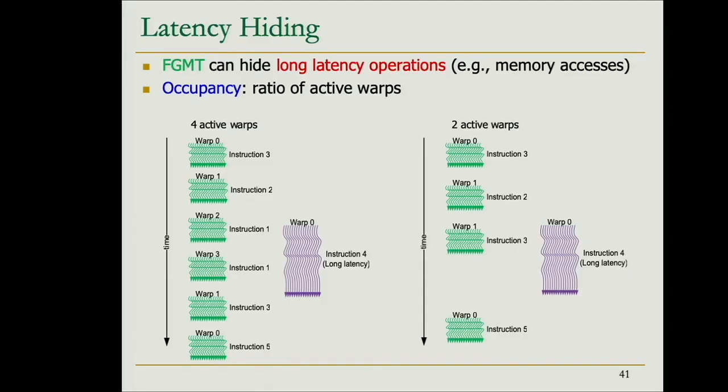So that's essentially what limits the maximum number of warps that we can have inside each of the GPU cores. But then there are more limitations, because depending on the program, the resources that these different warps need are different. That will depend on the program. We might have programs where we need, let's say, 2 registers per thread. That will depend on how good our compiler is as well.